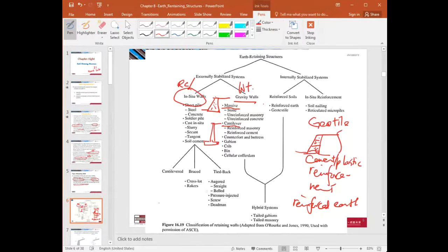So you have a wall here. That is the plain concrete. And here you have the RC. So you have to fix reinforcement and then pour the concrete to make an in situ RC cantilever retaining wall. And you may also have the counterfort. We'll come to that later.